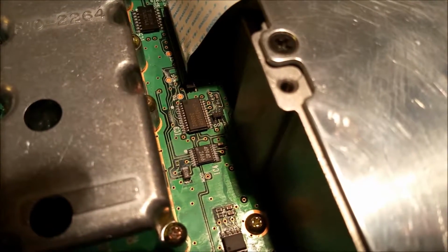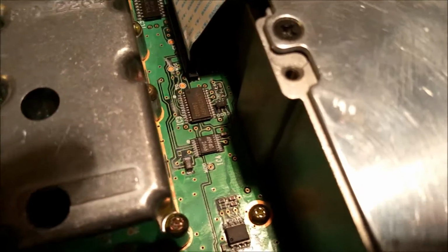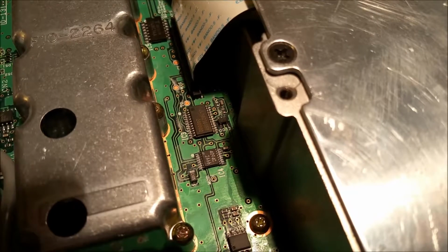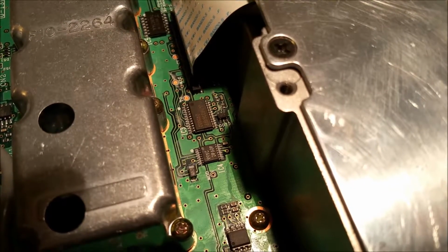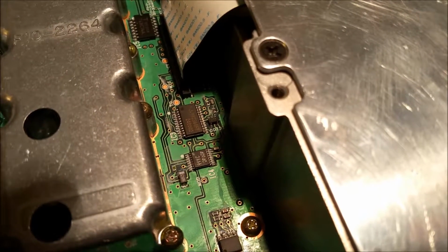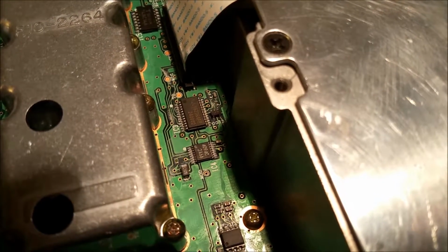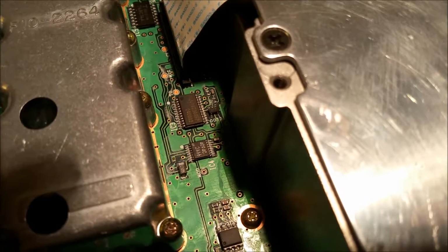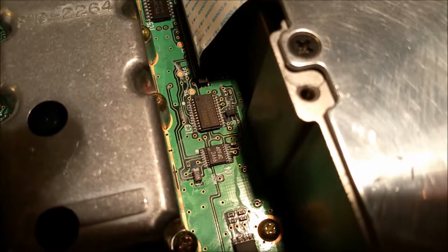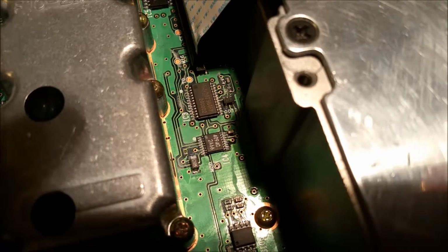And it solves my problem. So if anyone else is trying to use these with the All-Star RTCM to generate PL tones and having that same issue I have with, you know, having the audio mixed on one port out of the RTCM, you can now inject that audio into this mod port, and it will modulate the transmitter as if it's a flat audio input.